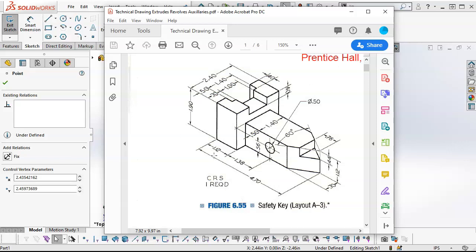Also, we have to make some decisions about our tolerances and stack up. So when I see the 1.12, I instantly think 1 1/8 or 1.125 as the 3 decimal place, taking it out to its non-rounded number. Same with the 1.38, I think 1 3/8, and that would be 1.375.